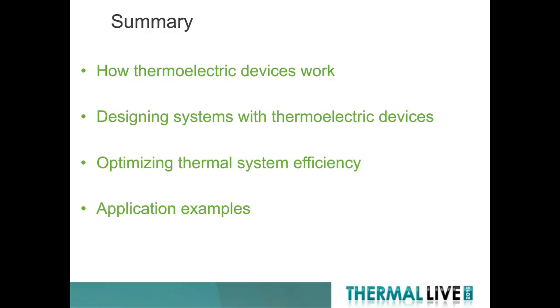As you can imagine, these are solid-state devices, semiconductor materials, so they're not like a metal block which you can pound on. They do need to have considerations for vibration, but we typically do vibrational testing and reliability testing of that nature on all the devices, especially those that go into the datacom and telecom markets. They're very keen on Telcordia type reliability structure testing. So they definitely can. Now, large temperature swings, a lot of it depends.